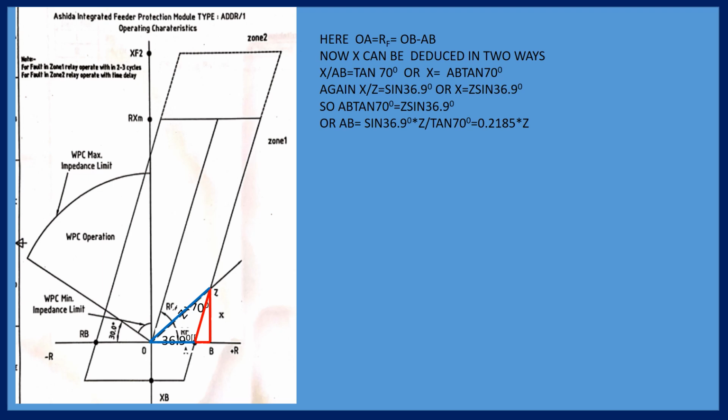And if you touch any metallic parts from the earth to the mast, you will get shock. It is called touch distance and step distance. So we are doing earthing to reduce the step voltage and earth potential also. Step voltage and touch voltage are kept within safe limits, so that we cannot get any electric shock.